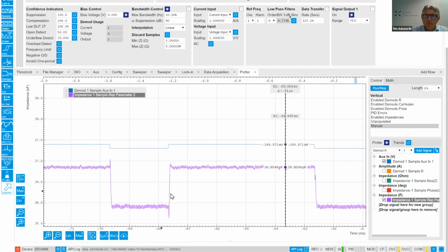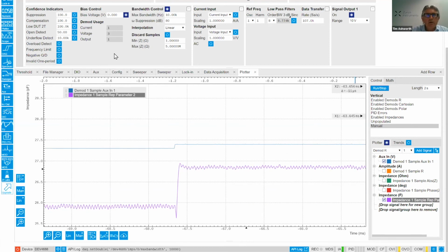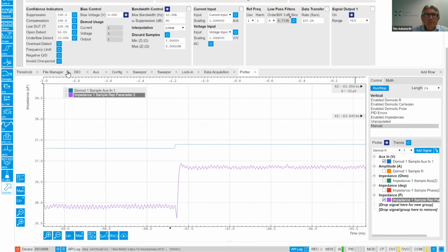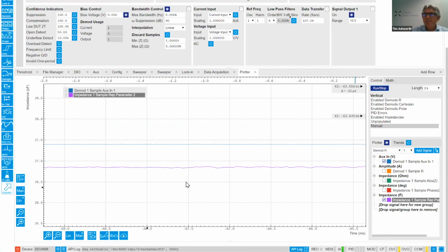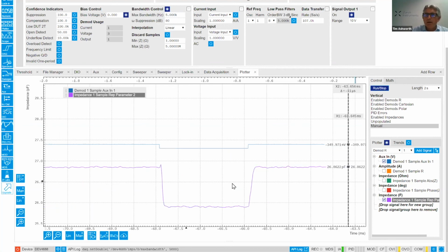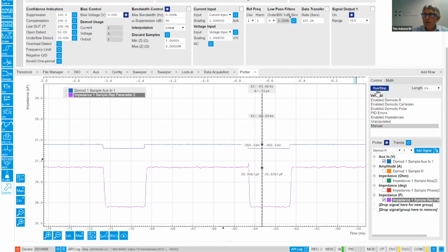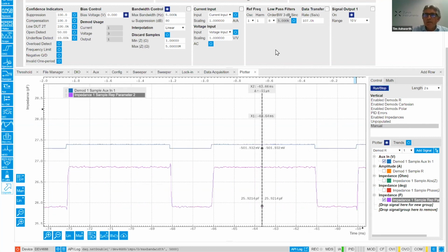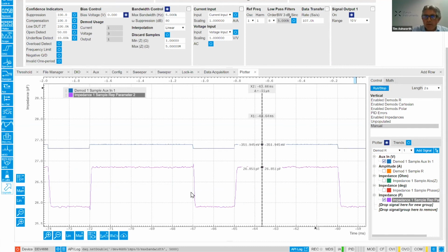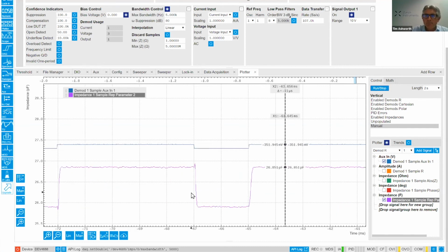Oh, we definitely have some resonance, a little bit of noise there. So let's indeed go down to maybe 5K. If your filter bandwidth is too open, it lets through the omega components, and that's what you're seeing there. So now we're filtering with 5 kilohertz, and that looks a lot better.